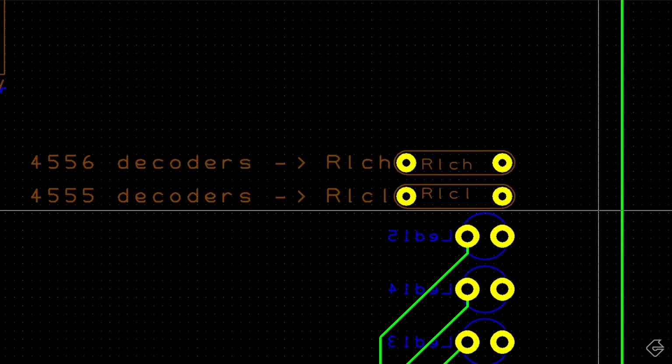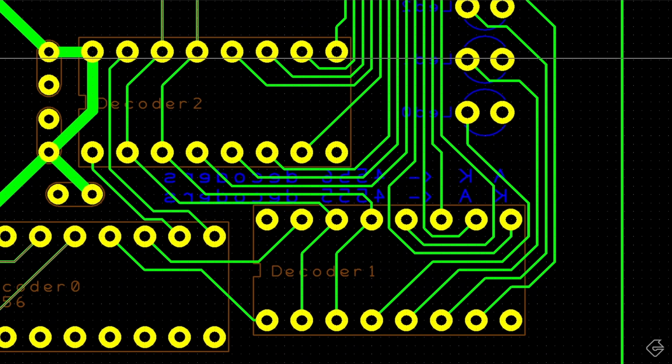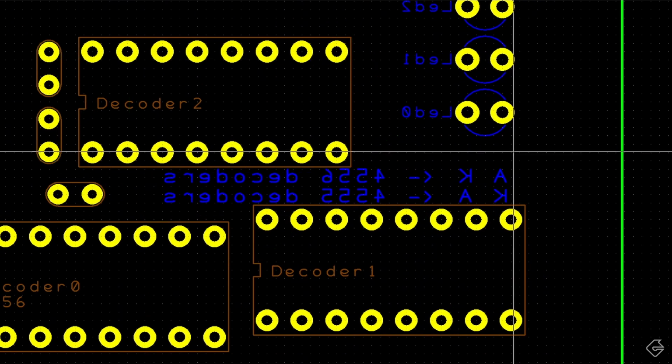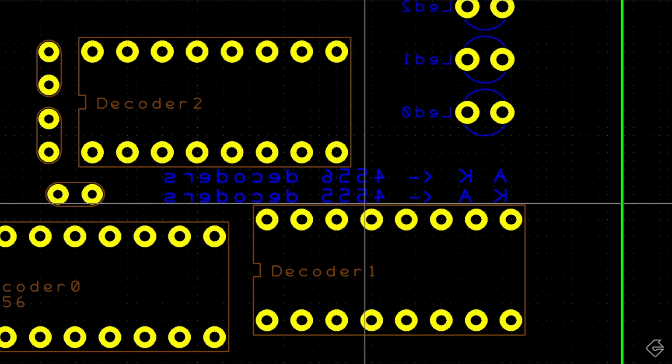Also, we want to decrease the chip count for our bill of materials. That's always a good thing when designing circuits. The less variety of chips you can use, generally the cheaper your product. But you do have to change the polarity of the LEDs. And so down here, let me turn off the copper so you can see it. I put another text on the board. Notice this is reversed, because this print is going to go on the other side of the board where you actually put the LEDs in. So that's where I want someone to look at this.